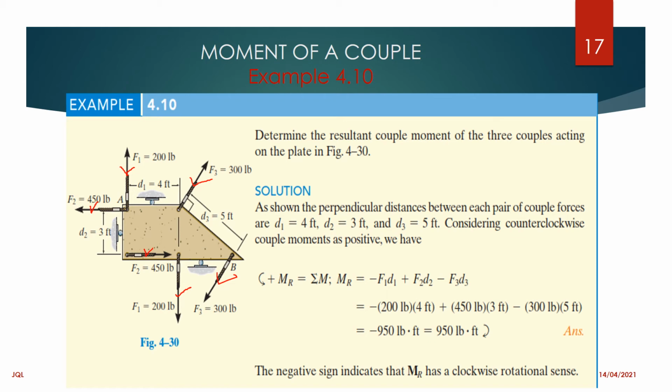How do we calculate a moment? We can remember that it is always the force times the perpendicular distance, right? Then the previous slide, I was teaching you on how to use these equations, summation of moments. But before you start doing your calculations, you need to agree on which signs you are going to use.